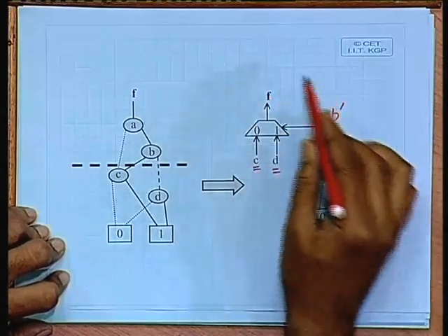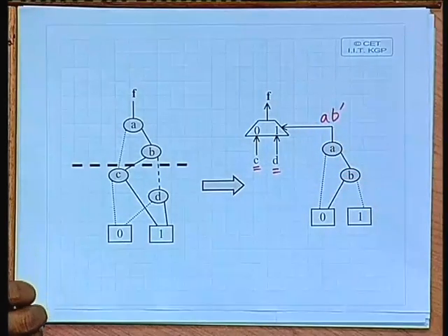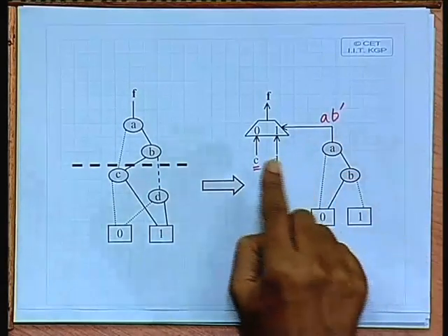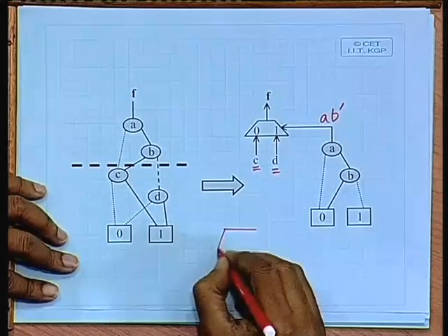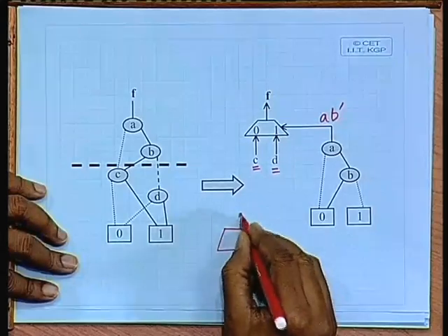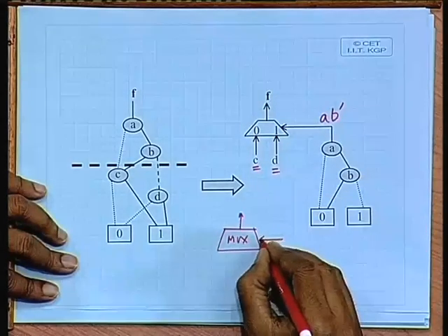So, you see that this way of synthesizing a function is in a sense hybrid. That means, you are not getting a purely gate level realization. There are some multiplexers, there are some small functions you get which you will have to realize using gates. Like here your final implementation will be, one multiplexer is needed, and here you need some function for A B bar.